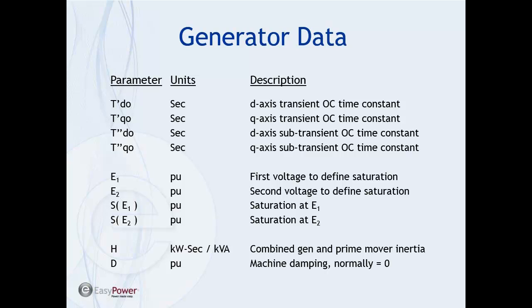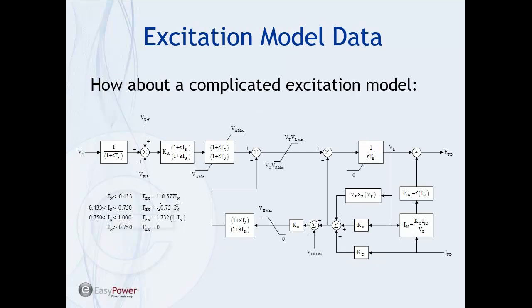Oh, okay. It used to be just, give me one single Thevenin value that represents the short circuit capability. That's what we do for ANSI fault calculations. Well, it gets a tad bit more complicated here because we want to simulate the real-time behavior. And then not only those, but now we have saturation and inertia. It just gets even more complicated.